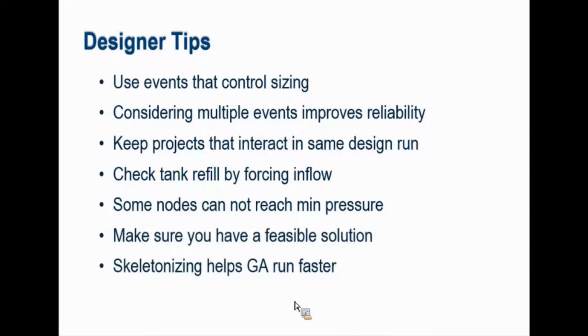And one other tip: skeletonizing the model helps you run faster, helps genetic algorithms run faster, but if you're really trying to size pipes in an area, maybe skeletonizing, simplifying your model may not be what you want to do.